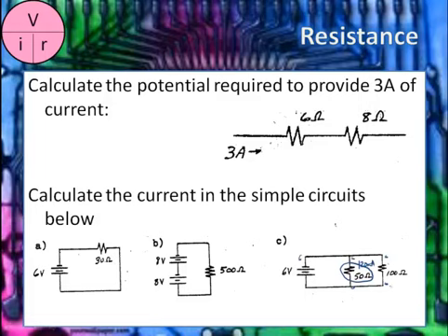And then here, 6 over 100 is half of that, so 60 milliamps runs through here. And so if 120 comes down through here, and if 60 comes out and goes around through here, then 60 plus 120 means 180 must go through this part of the circuit. So there's a few examples of current and resistance.